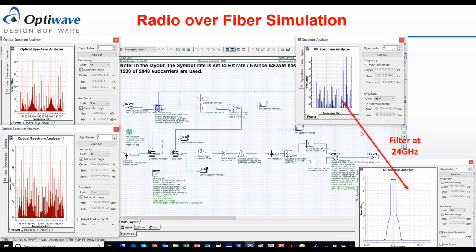Now, if you zoom in on these locations, as explained by Mahmoud, you can see here the RF spectrum of the modulated data. And you can see this is the pedestal of the spectrum, which is created due to the nonlinearity. With the scheme he is creating for linearizing the channel, you can get rid of it and improve the performance of the system, and reduce the error vector magnitude to the standard levels or below standard levels to allow the transmission. Now I'm going to move into the project layout.